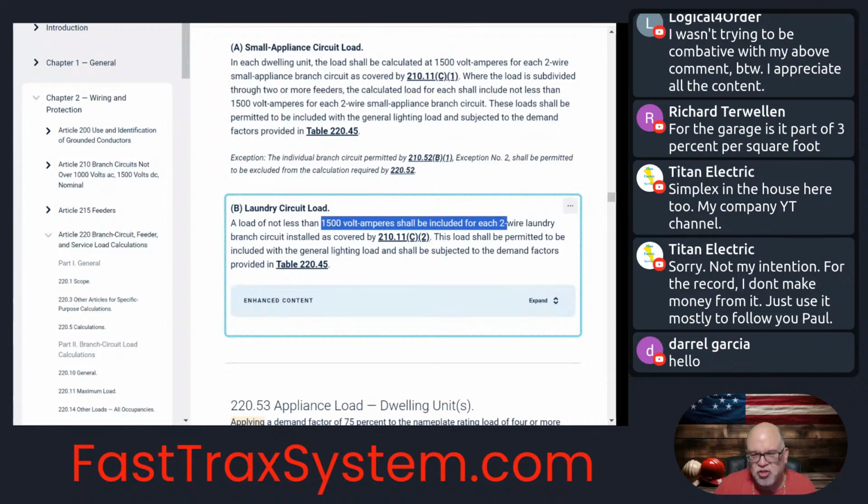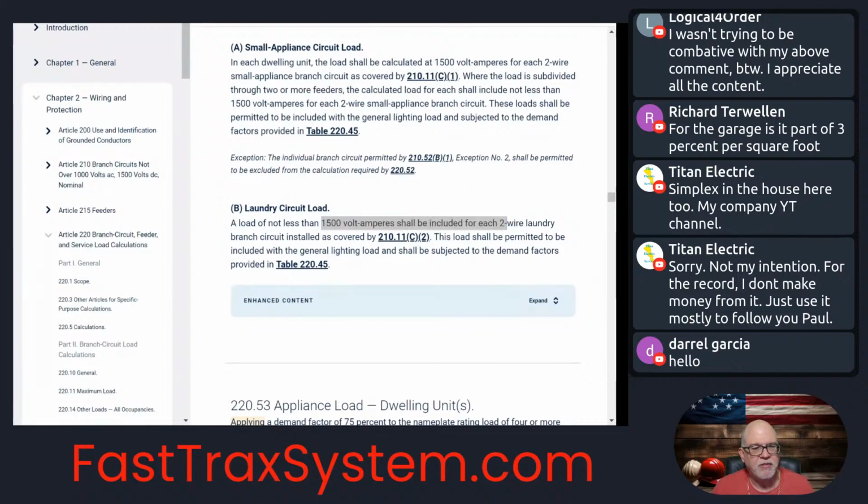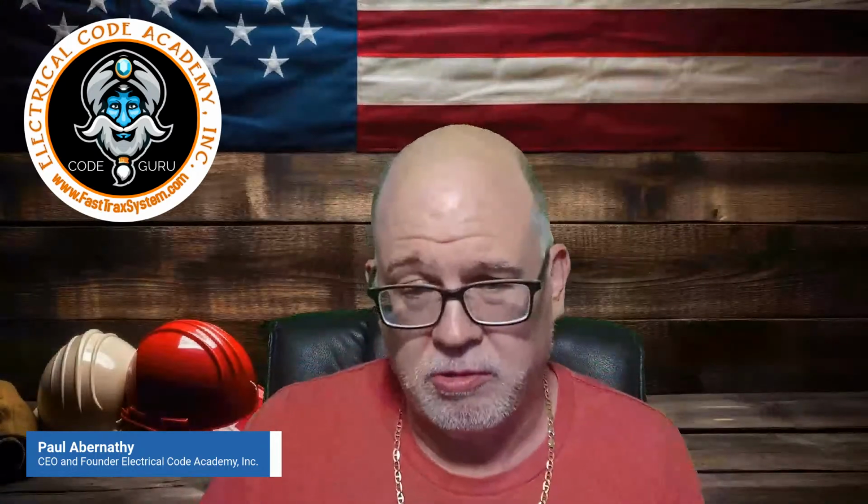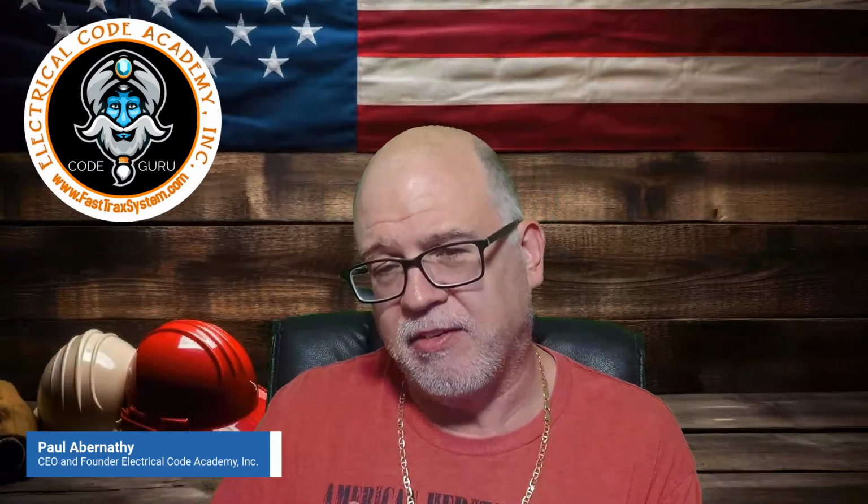2. That is so important too, because if you are calculating for somebody in the real world, you ought to know. For example, when I'm doing this 10,000 square foot calculation for the house that my brother's wiring back in Virginia, I know that they're going to have more than 2. So I have to look at it and say, well, it looks to me like we're going to have at least 5. So I have to take that as 1500 VA each for 5 of them, that type of thing, okay?